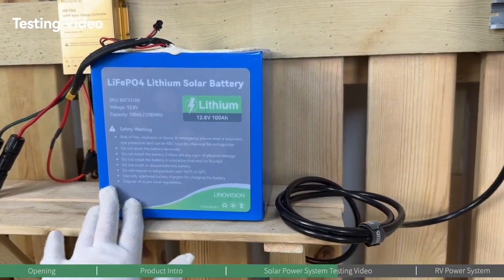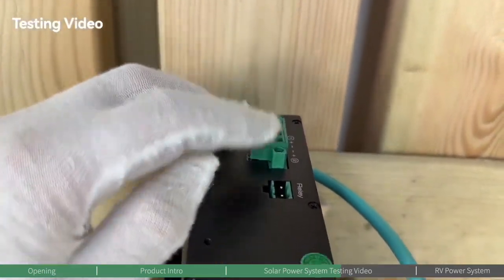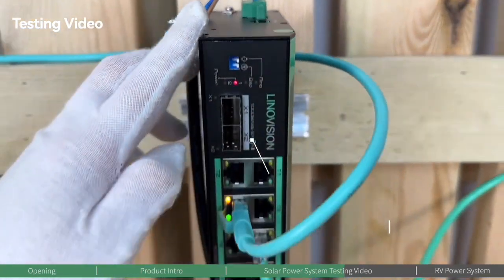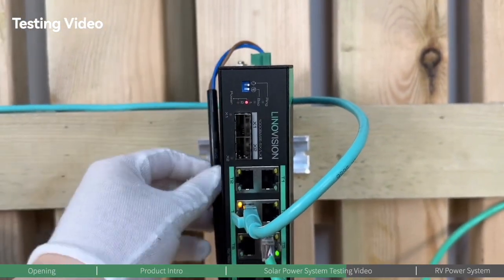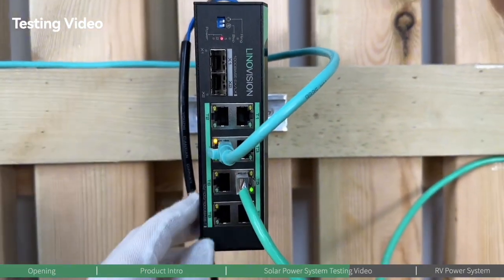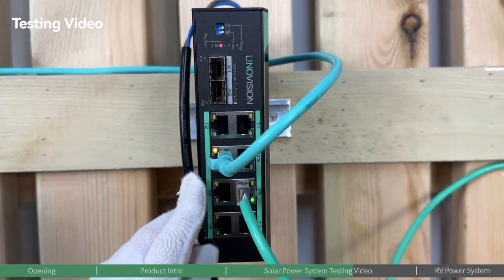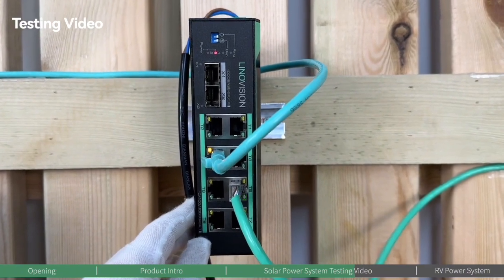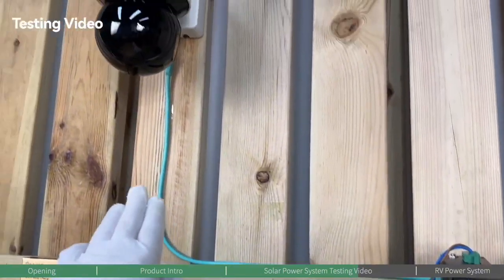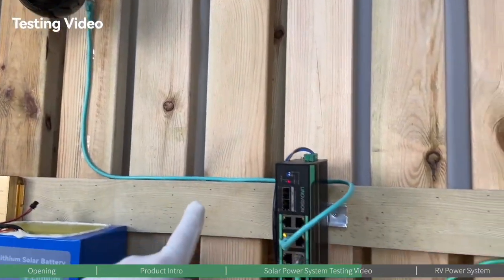And then the DC 12 volts is directed to the central device in today's setup, the wide voltage input PoE switch from LINOVISION, which receives the DC 12 volts from the battery. With the voltage booster feature, it's designed to work with a voltage input range of DC 9 volts to 48 volts, and then outputs the PoE standard 48 volts for PoE devices, accommodating typical PoE compatible devices.